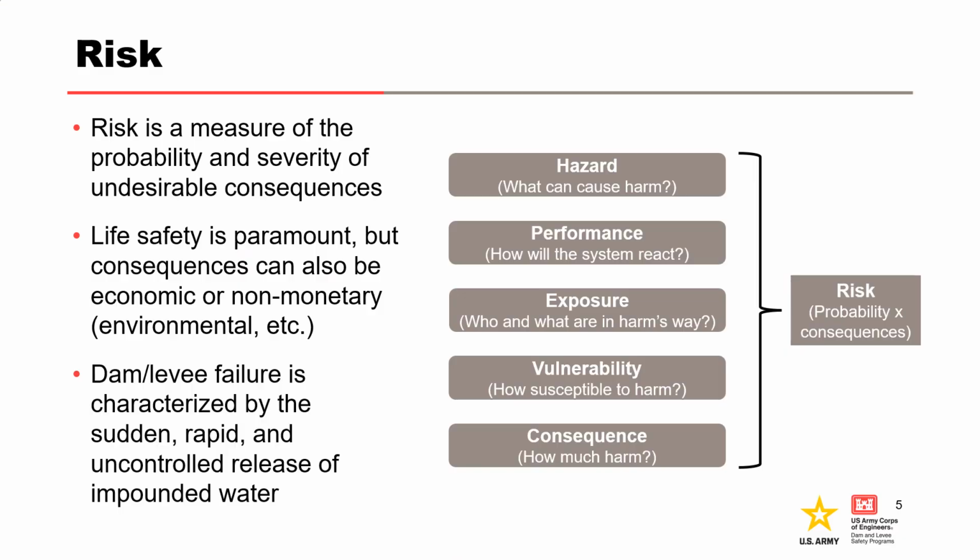Risk is a measure of the probability and severity of undesirable consequences. For dam and levee safety risk assessments, these undesirable consequences can be associated with life safety, economics, or non-monetary consequences like environmental destruction. Of these different sets of consequences, life safety is paramount and the primary factor that guides our decision-making process for dams and levees.